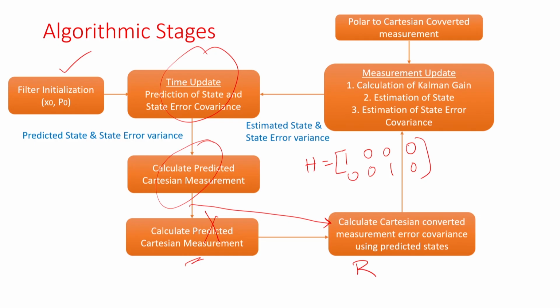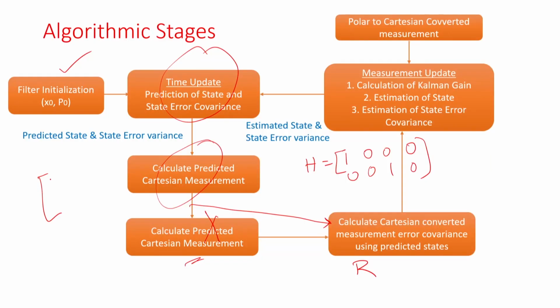This is very important for how a pseudo-linear filter works. The difference between a linear filter and an extended Kalman filter is that with a linear filter, only your R matrix is going to be updated each and every time. Now, there is an important thing: my states are x, x dot, y, y dot, and my measurements are now xm, ym.